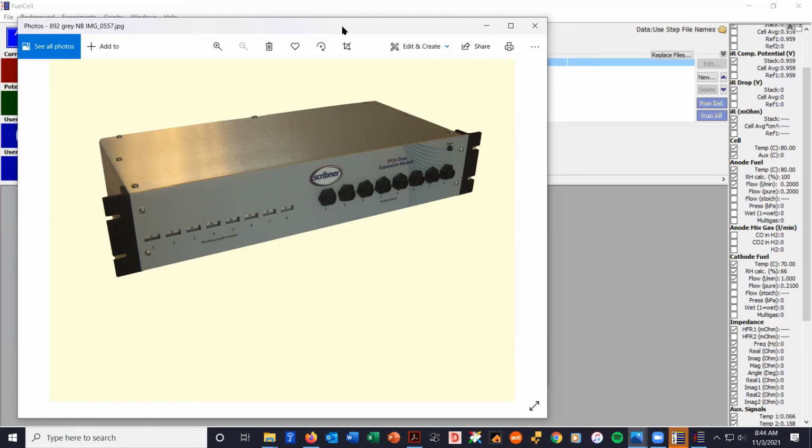Good question. I also see that these analog inputs have at least 4 or 5 voltage ranges, right? 150 millivolt, 500 millivolt, 1 volt, 5 volt, and 10 volts. You're looking at the data sheet.